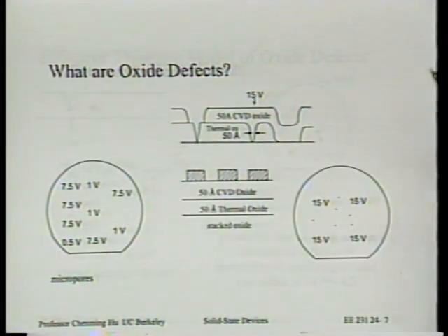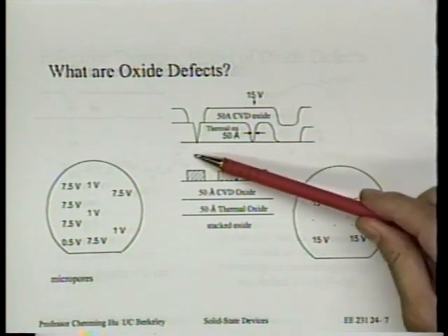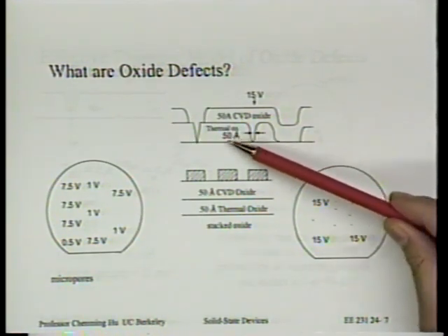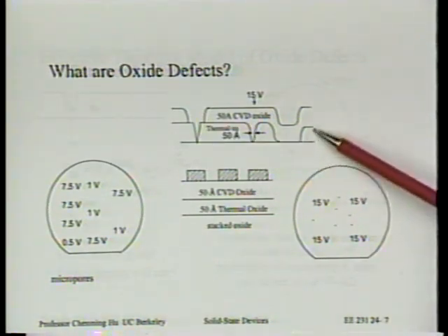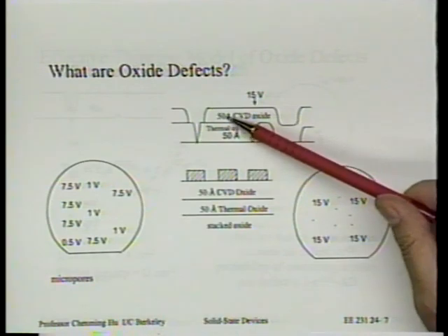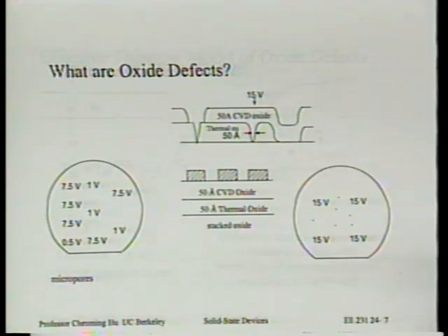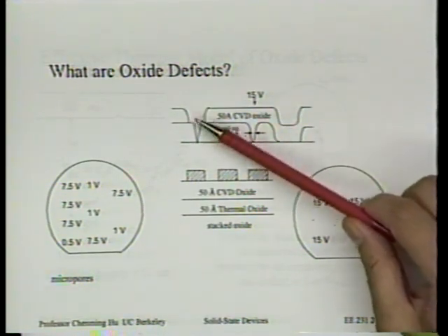Let's look at what defect may mean, all right? First here, schematic, we show what's the defect for that first 50 angstrom of thermal oxide, right? We just showed quite a few defects here, all right? Okay? Next, we'll put another 50 angstrom layer of CVD oxide on it, all right? It's probably unlikely you'll be so unlucky that there are 2 defects lined up in these 2 layers.